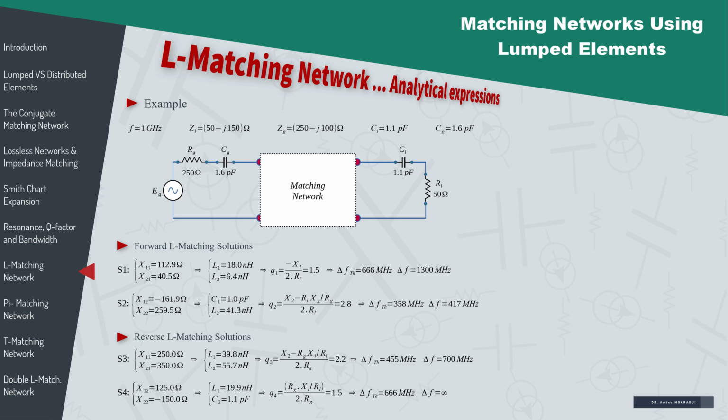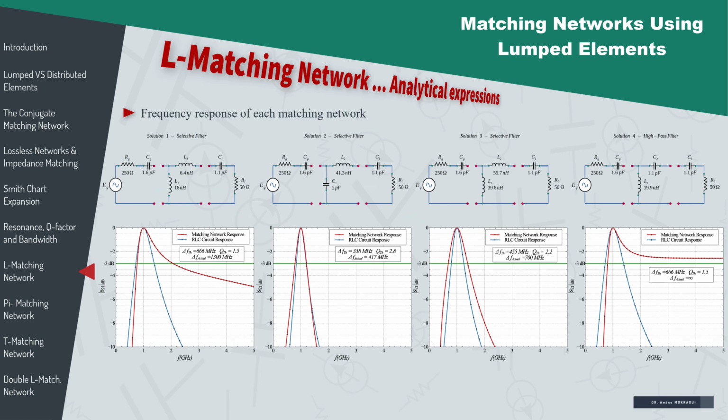Based on this example, it appears that the Q factor only brings a general indication of the bandwidth, but it still gives us a qualitative indication, helping us predict which circuit will have a greater bandwidth. The following figures illustrate the behavior of the transfer function S21 of f of the matching network, while comparing it to the response of an RLC circuit characterized by the same Q factor.